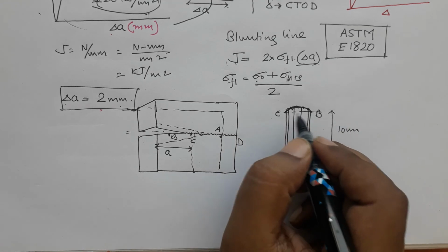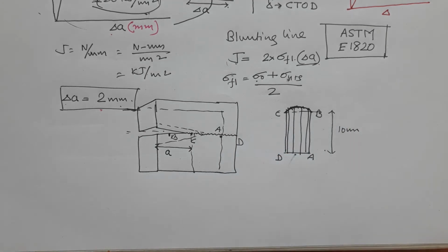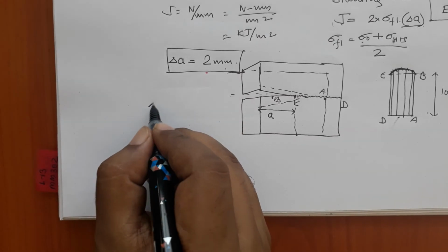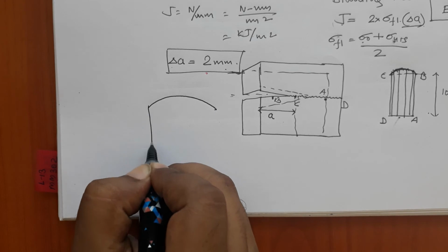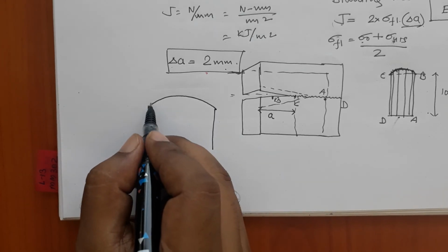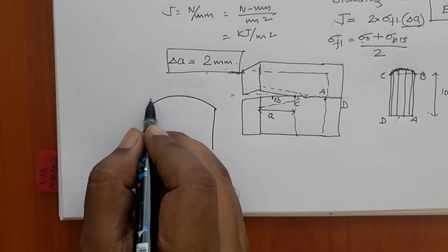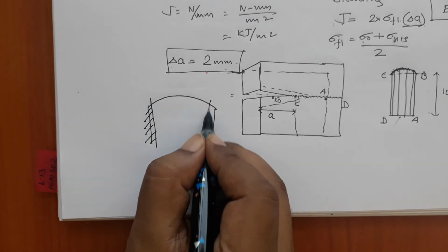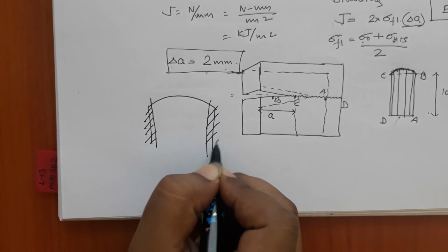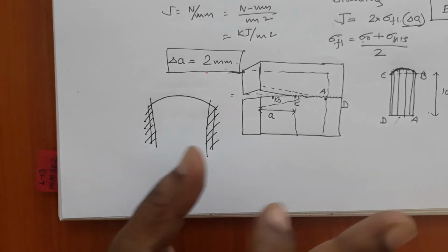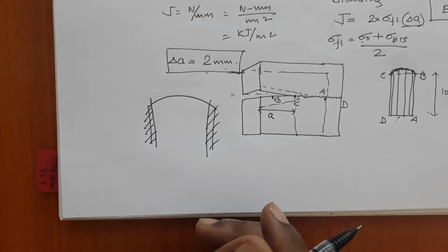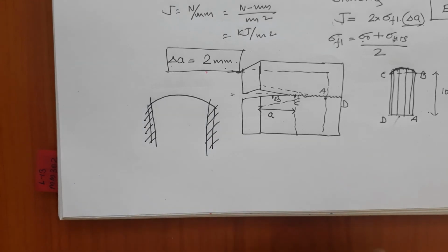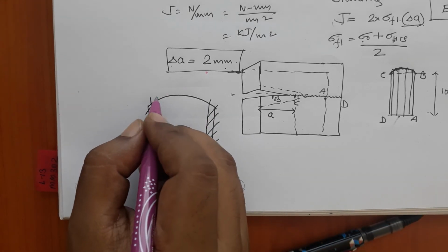equidistant from each other, and then there are some protocols to avoid problems. So what the ASTM standard says is, like, if this is the crack tip, so what you do is, first of all, the standard says that you exclude some portion from the surface, okay, because at the surface you usually have plane stress conditions. So, you do not want to take that part in the calculation, right. Then the remaining part you divide it in 10, sorry, you have to take 9 points.